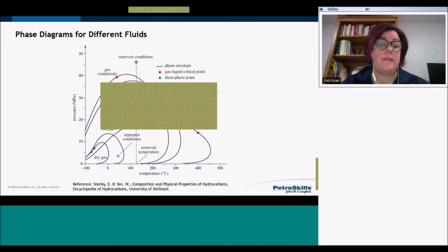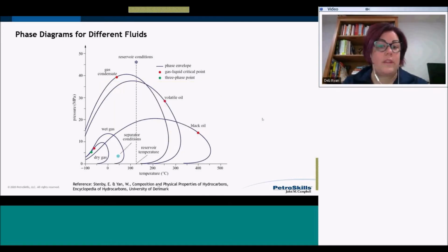So I know that doesn't necessarily help with the answer on that in terms of how they do it, but it's also one of the reasons, and I stress this, that it's so important for us to get lab work done, for us to get samples of our actual oil and understand how it's going to change and behave as we change the reservoir temperature and pressure in our reservoirs, and how we can then optimize our performance. But they are unique for every single reservoir fluid.